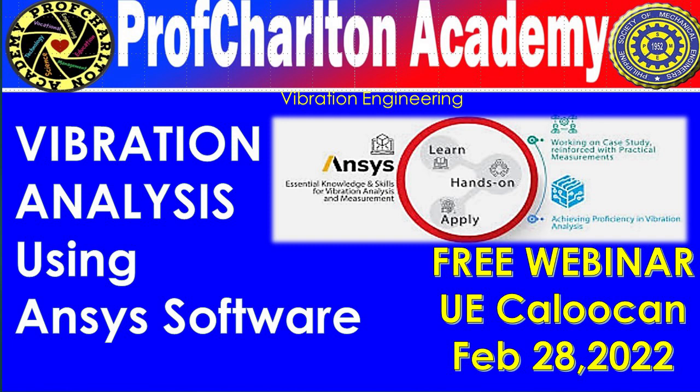When you go into the engineering data, you can create your own materials. We also have a library that you can use directly. For example, we have structural steel, for which the material properties are already defined. Young's modulus is 2E11 Pascal. Poisson's ratio is 0.3. We need these two properties to identify the stresses generated in the material. These two are the most basic properties needed to get the stresses.